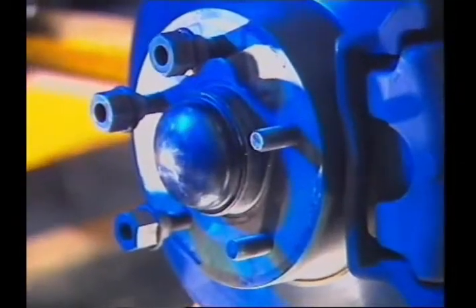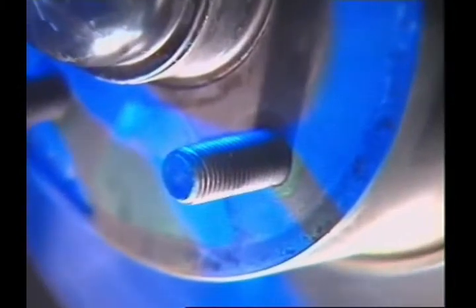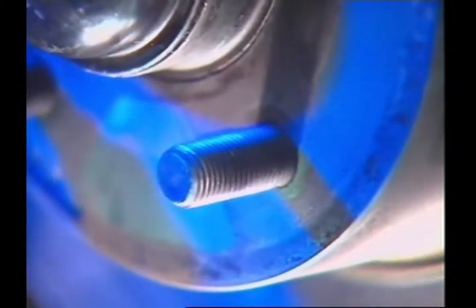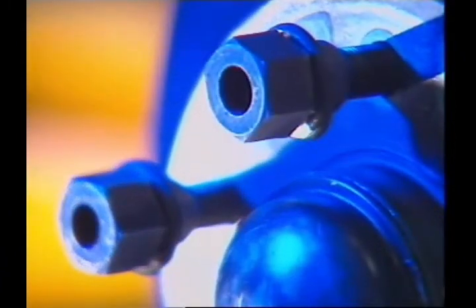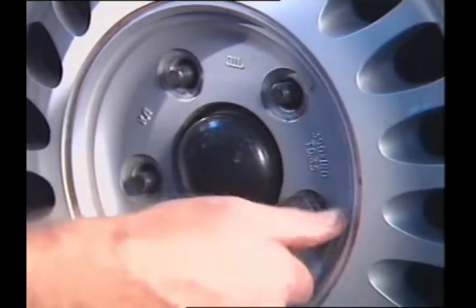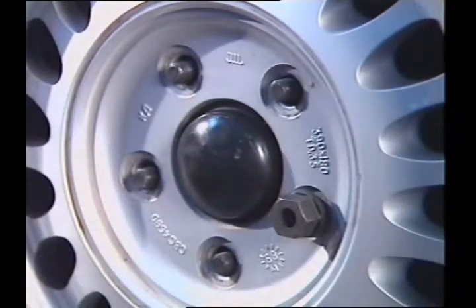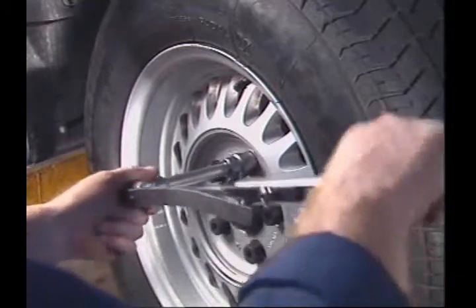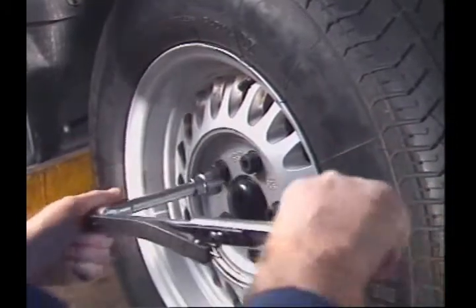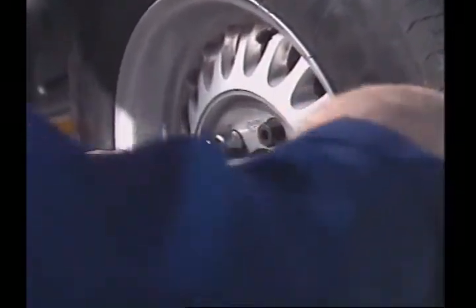Wheels are fastened to the hubs by wheel studs and nuts. They're highly stressed by loads from the weight of the vehicle and the forces generated by its motion, and they're made from heat-treated, high-grade alloy steel. The threads between the studs and nuts are close-fitting and accurately sized. All wheel nuts must be tightened to the correct torque. Otherwise, the wheel could break free from the hub.